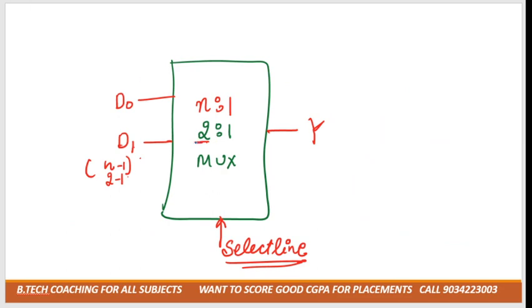So for 2 is to 1, how many select lines will we use? Only 1, because 2 raised to power 1 is 2, so there is only one select line. That is denoted by S0. In digital, generally we don't start with 1, we always start with 0. 0, 1, 2, 3, 4, and so on. Clear? So this is the basic block diagram of the 2 is to 1 multiplexer.